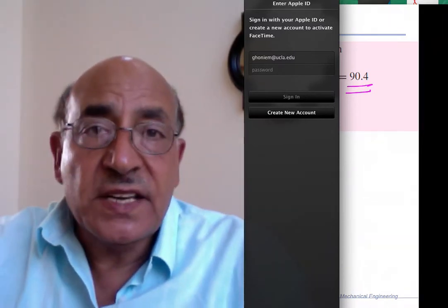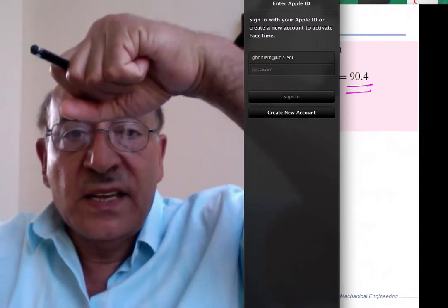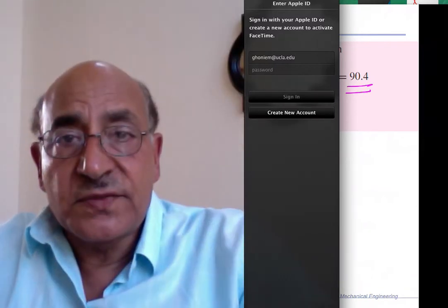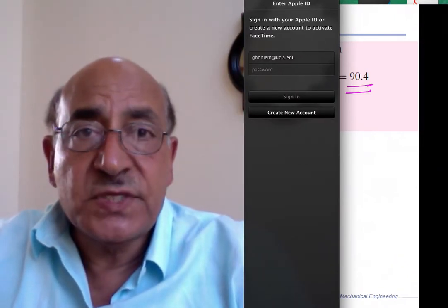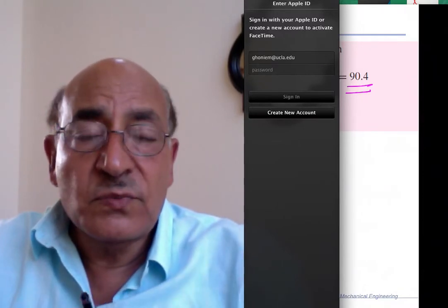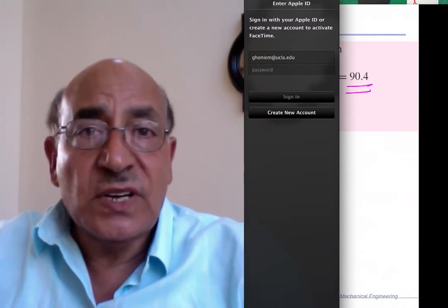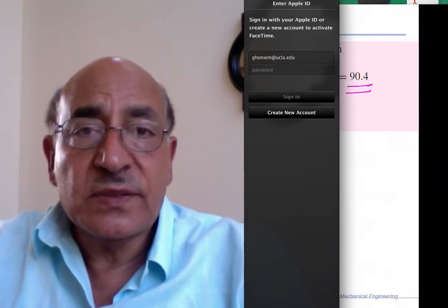You have some inertia in there. So the method we use is going to be simple. If we have a falling object on a surface, a beam, then we calculate the potential energy, and then we're going to assume that there's no momentum transfer to make our life easier, so there's no bouncing back and forth and momentum transfer.